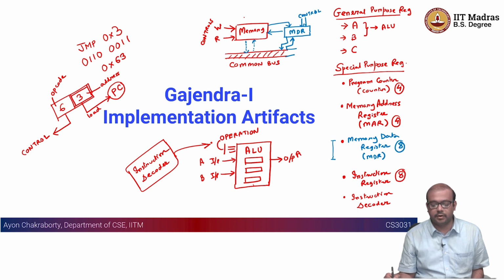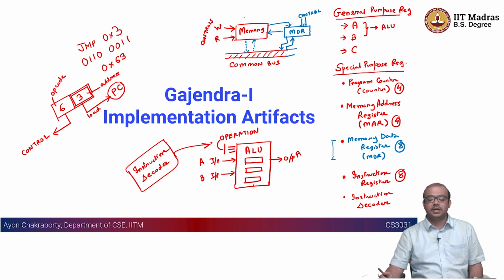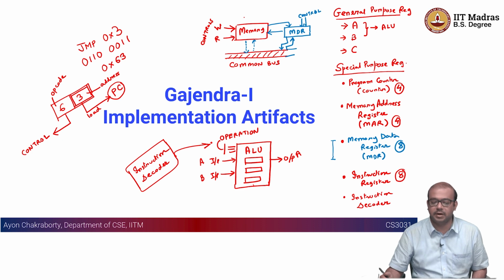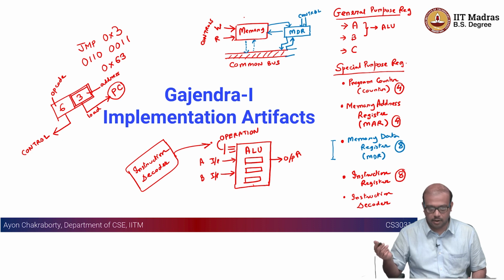Our opcode for addition was 3 and the opcode for subtraction was 4. So there are definitely two different lines that are going to be activated through the instruction decoder, and we can feed that to the ALU to indicate that you have to do an addition or a subtraction. If you have more operations, let's say 4 operations in the ALU: addition, subtraction, or and not, you should use 2 bits to indicate that, and those 2 bits will come from the instruction decoder, right?